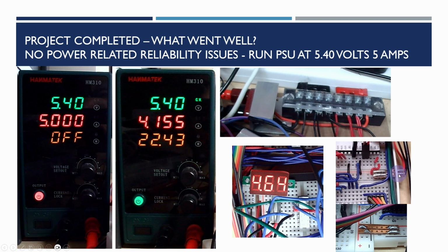So these connectors I've made, which are soldered and have generally about 3 pins on each power rail to ensure good connections. I did try using thicker wire for these, but the problem I found with thicker wire is these connectors used to then lift out. So in fact, there's a trade-off between using thicker, lower resistance wire and this hookup wire. I found this to be more reliable.